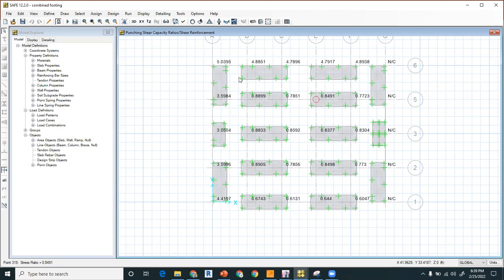So the first solution is to combine all of these external footings to make a strip, but still it will not work because it is 3 stories and it is not recommended to combine these, because there is still an issue. But the best option is to provide a straight beam here, because it will be economical compared to combining all of these strips together, right?